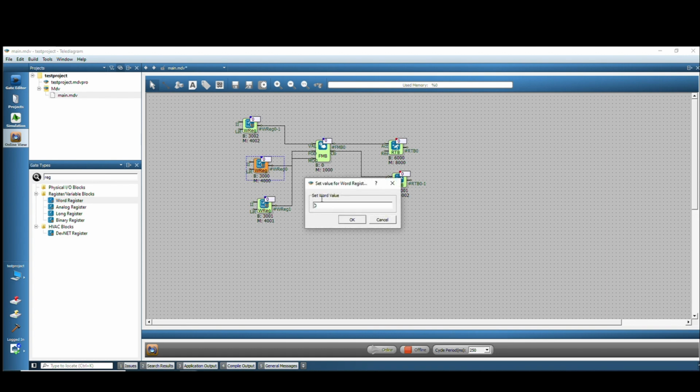Now let's set the full opening time to 10 seconds. We set it to reach 10 seconds and minimum to 0. It will reach from 0 to 10 seconds. And we entered 50 as the value, expecting it to reach 50% change, meaning it should achieve full opening for 5 seconds.